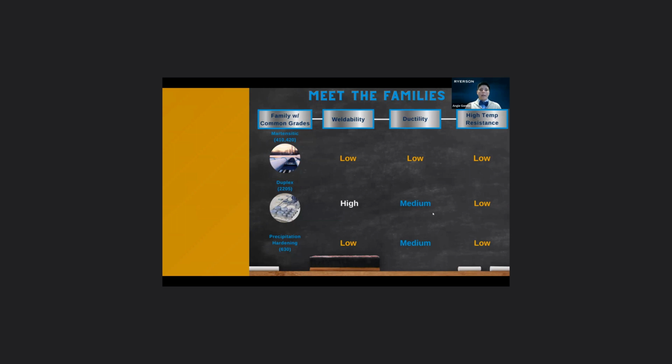Oil drilling and water treatment operations use duplex a lot because it's actually stronger than 316 and better at corrosion resistance. Precipitation hardened, also known as pH grade, is actually a hardening process and less about its chemistry. It's a heat treating technique which is used to increase the tensile strength of the material. These materials are usually found in aerospace and high-tech applications like gears, valves, and other engine components.